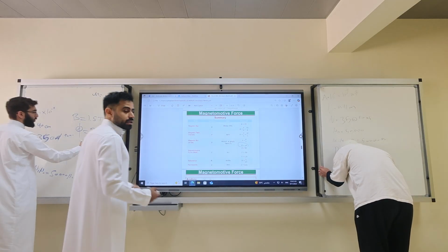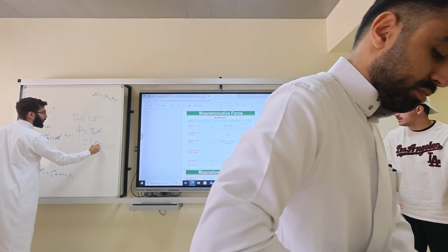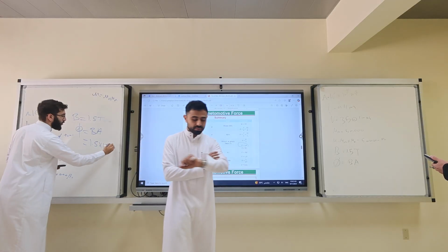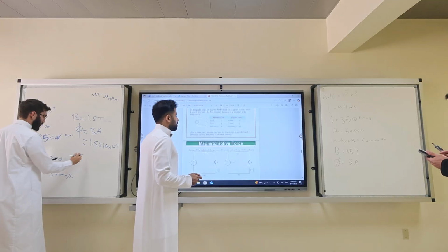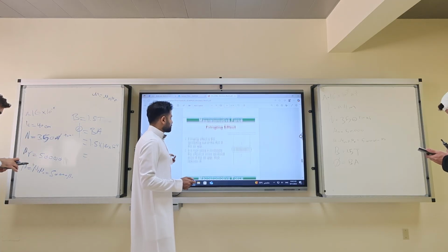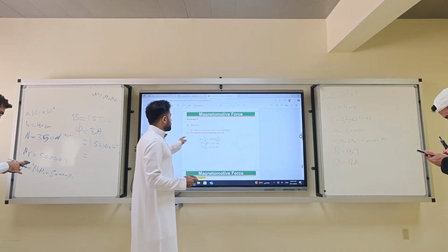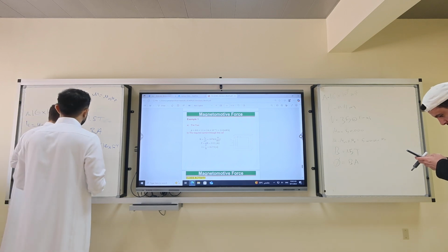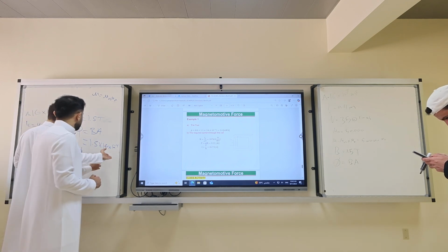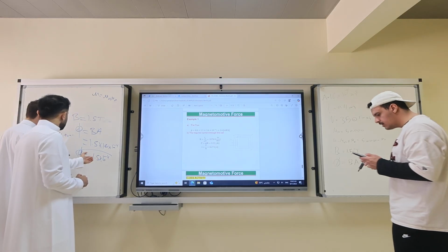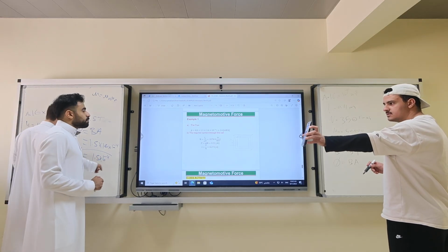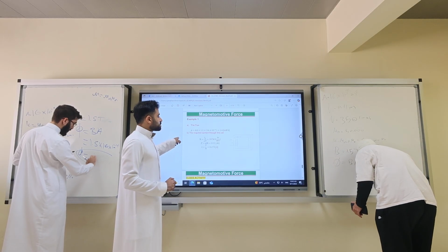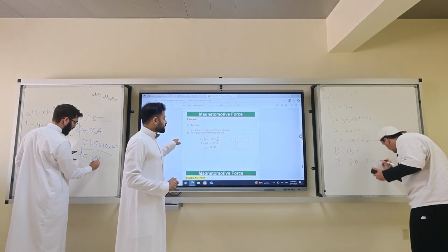Okay? Calculate. Please, finish the exercise. We don't have time. 1 minute left. What is 1.5 times 16 times 10 to minus 4? Don't write everything. Multiply directly. No, you already did the multiplication. What's the answer? No, that's wrong. 2.4 milliweber. Now, to get the current, you have to get the reluctance.